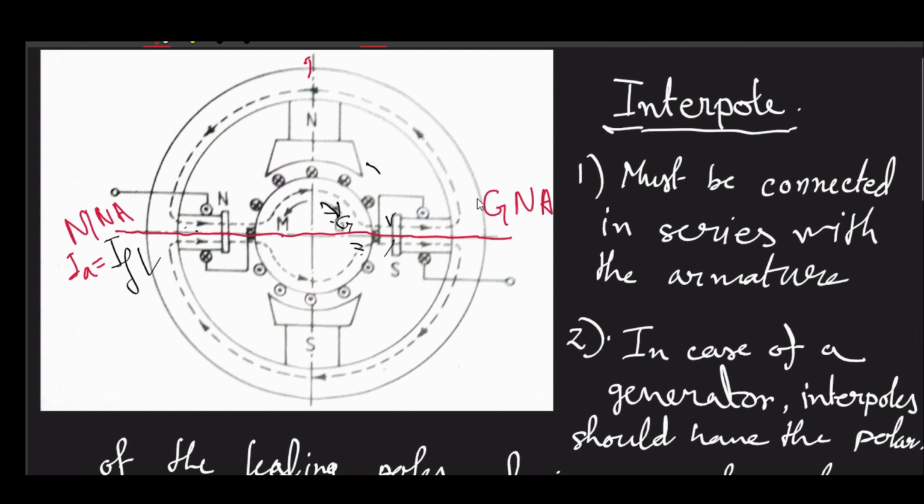Like here, you can see that main pole shoes are curved, but interpole shoes are straight to enhance the reluctance in the path. But that will do what? It will produce a chance of huge leakage reactance, and that leakage reactance is in no way desirable.